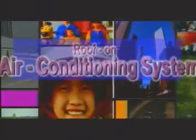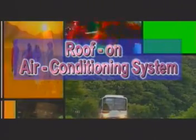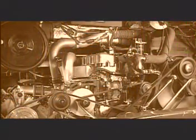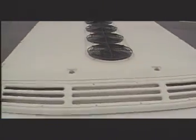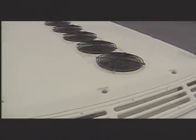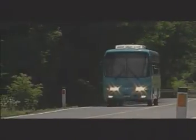This video has been produced for the technical service training of the bus roof-on air conditioning system. In the roof-on air conditioning system, the engine drives the compressor by a belt, and the evaporator and the condenser are installed on the roof of the bus, and the fan and blower are driven by electrical power.